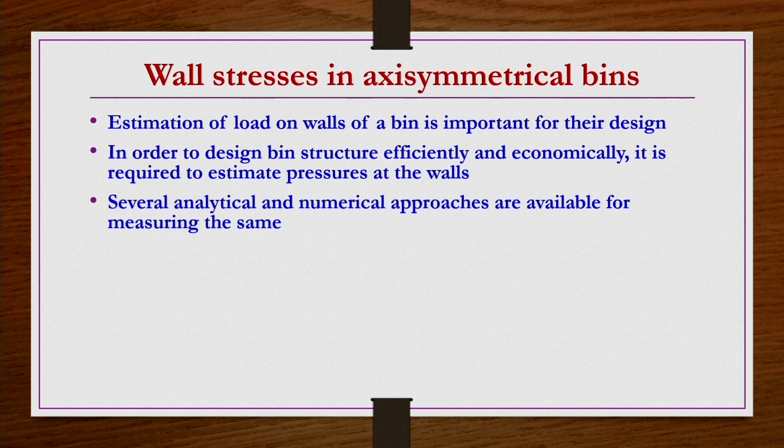Okay. There are several analytical and numerical approaches available for measuring the pressures. In general, so many numerical tools are available. Using the numerical simulation packages, one can estimate the pressure at each and every location inside the bin, both in the static as well as the dynamic conditions, and then one can have a clear picture of how this pressure is varying point to point, right.